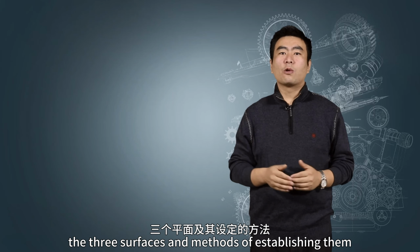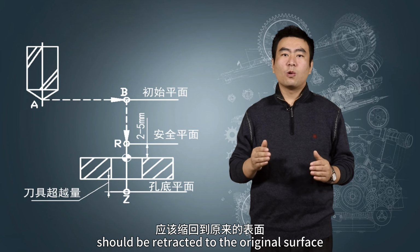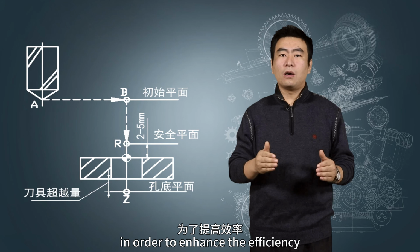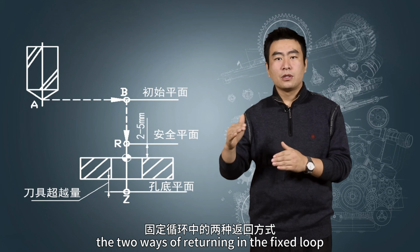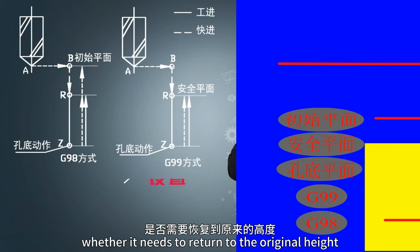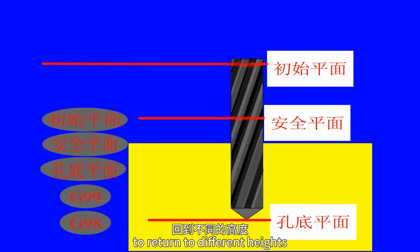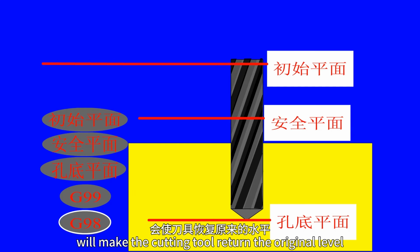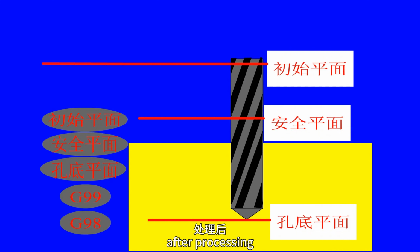Since we have learned the 3 surfaces and methods of establishing them, please consider whether the cutting tool should be retracted to the original surface of the program every time we process a hole, in order to enhance the efficiency of the subsequent processing. We need to talk about the 2 ways of returning in the fixed loop, in order to determine whether it needs to return to the original height. In the 2 ways, different G-codes control the cutting tool to return to different heights, so as to meet different demands. For example, G98 will make the cutting tool return to the original level, but G99 will make it return to the safe surface after processing.